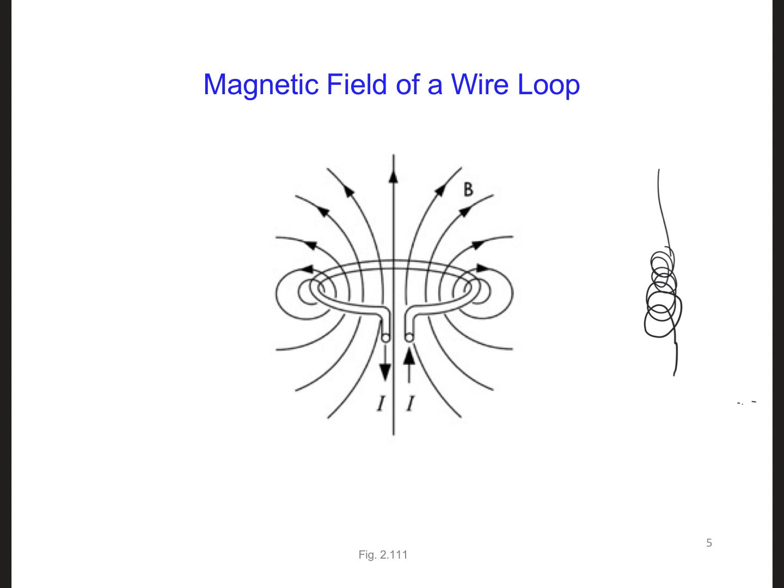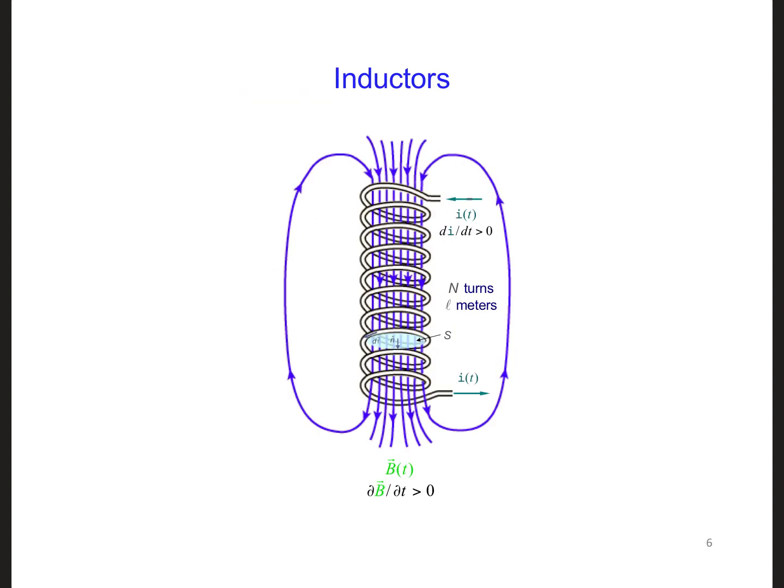And you might have seen this before. This is called an inductor, and it's used to store magnetic fields. These purple lines here are the B fields. It can vary in time, and we can use it to store magnetic field energy. And so let's develop a voltage current relationship for this inductor, because then we can start to use it in our circuits if we have that relationship.